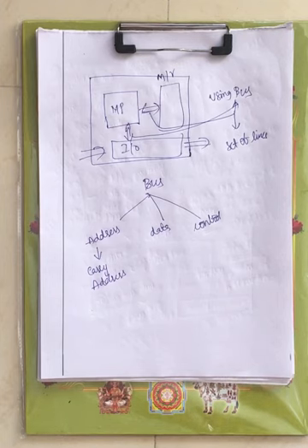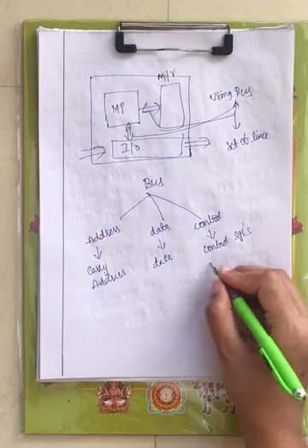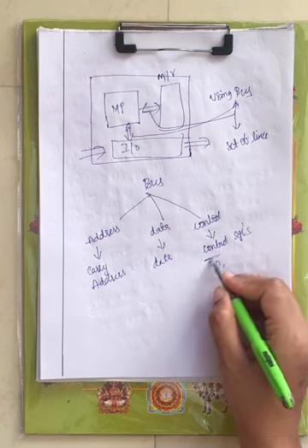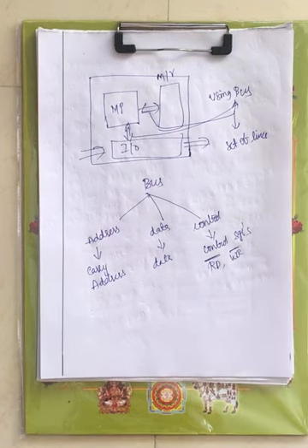Now what the control signals are, we will see under the architecture of a processor. This includes the read signal, RD bar, which is active low, and the write signal, WR. You will have a clear idea while discussing the architecture. Meanwhile, just remember, in order to transfer information between devices, memory, the processor or IO devices, we use the bus.